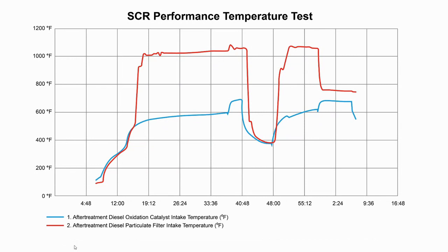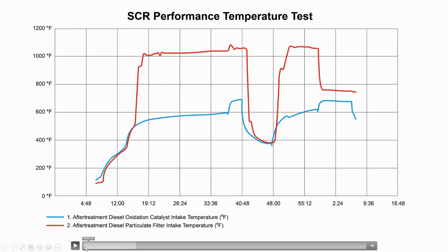So we can see around that 500 degree mark, that temperature increases very, very quickly from the first sensor to the second sensor. That second sensor is after the DOC, and we can see that temperature increase at the point when it was able to dose the hydrocarbons in there. So they mimicked one another up to that point. Then once hydrocarbons got dosed in there during this performance test, it's a forced test usually during startup conditions of most diesel vehicles. It'll go through its own test to see if this is working properly. So the second sensor says, now guess what? Now I can build up a lot of heat in the system. Everything really looks good. So now let's continue on.